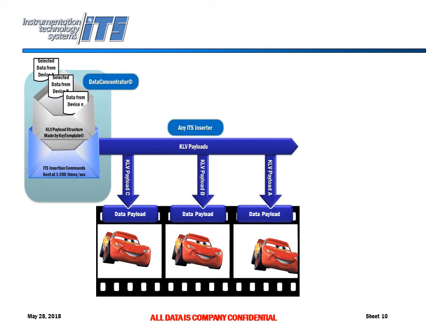The beauty is that the data can be coming to us as payload packets much faster than the frame rate, so that what you have is data that's very close to the start of each frame, as our equipment then subsamples the data on the start of active video on the first line of every frame. So it's a consistent place regardless of the format.